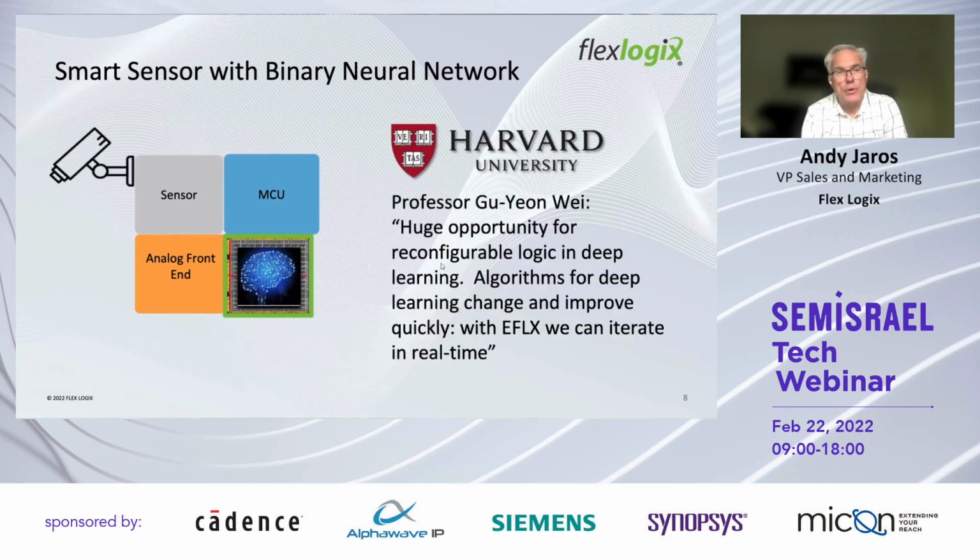Additionally, by using binary neural networks, you can actually do some AI processing on a relatively small number of LUTs with a small amount of embedded FPGA. Again, this extends the processing capability above a reprogrammable state machine to actually doing some AI functionality in sorting at the sensor level itself.